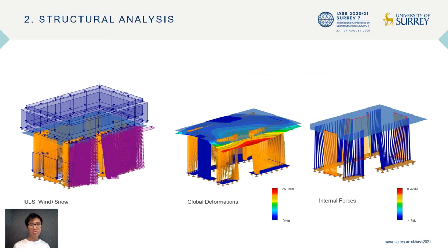The location of the 9 stands played a huge role in influencing the design. During the structural analyses, it emerged that the combination of wind and load were the governing load cases. The remote location of Turrach Höhe, for example, sits at approximately 1800 meters above sea level. It has a characteristic snow load of 7.3 kilonewtons per square meter and a maximum wind speed of 140 kilometers per hour. In the calculation model of the lamellas, an elastic plastic load-bearing behavior was assumed.